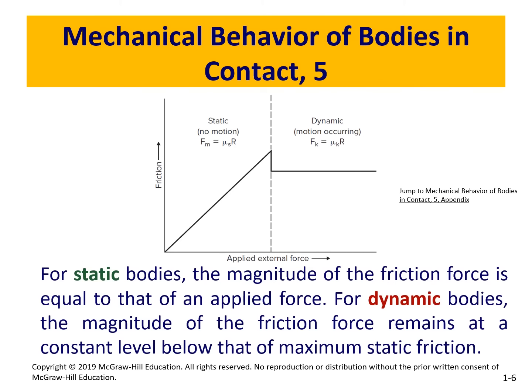And this is it. So this is the schematic. If you look here, the y-axis is the friction force, and the x-axis is the applied external force. As we increase the applied force, the friction force increases, but here the object is not moving. We continue increasing the applied force, and the friction force increases until we reach the maximum static force here.